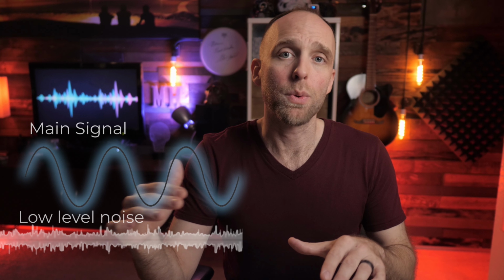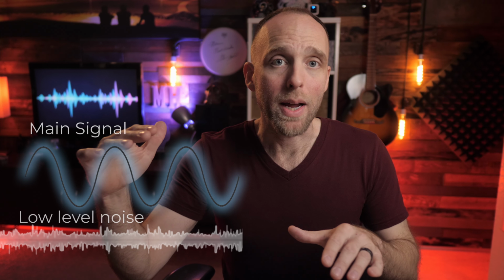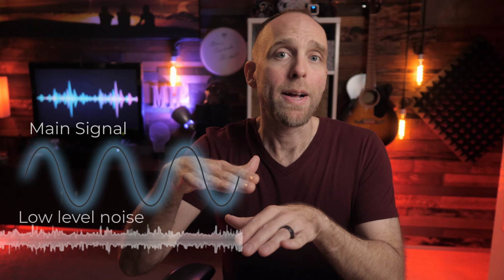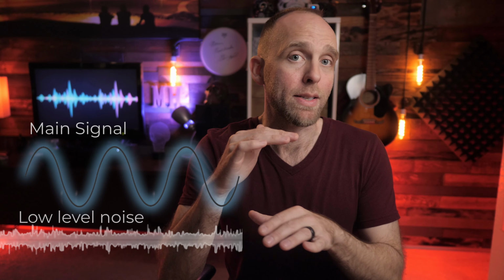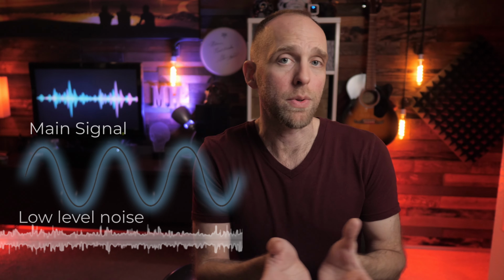So the next device will then have to boost that signal. And that next device, like a preamp, will be amplifying our main signal, which is now a lot closer to the noise floor. And that next device will also have its own inherent noise as well, and that preamp may have more noise than your main signal. So the preamp's noise will also then get amplified and sent through the system.